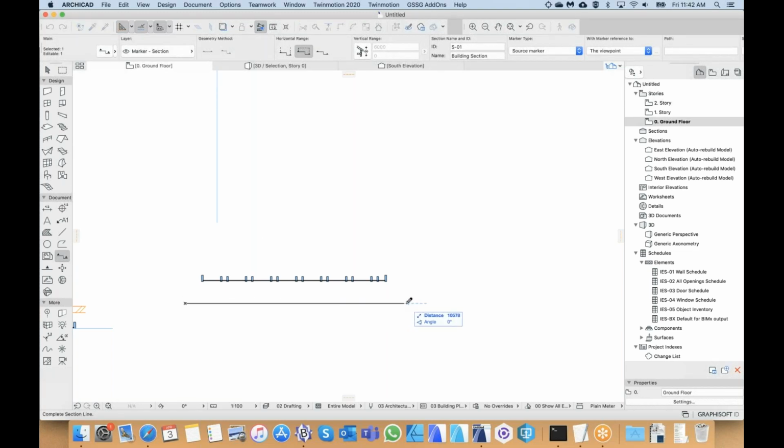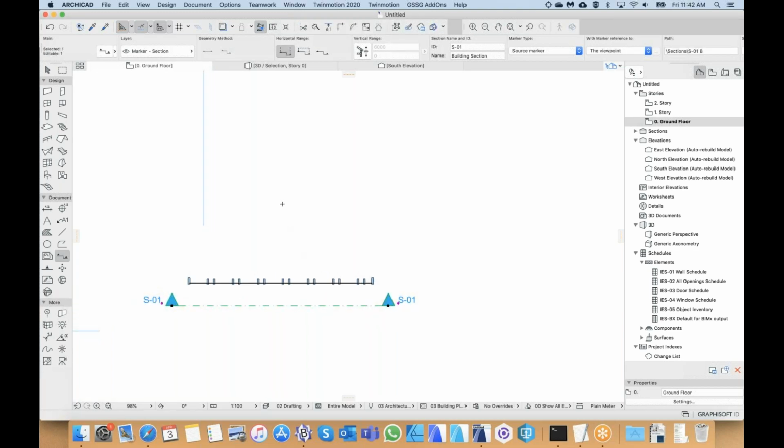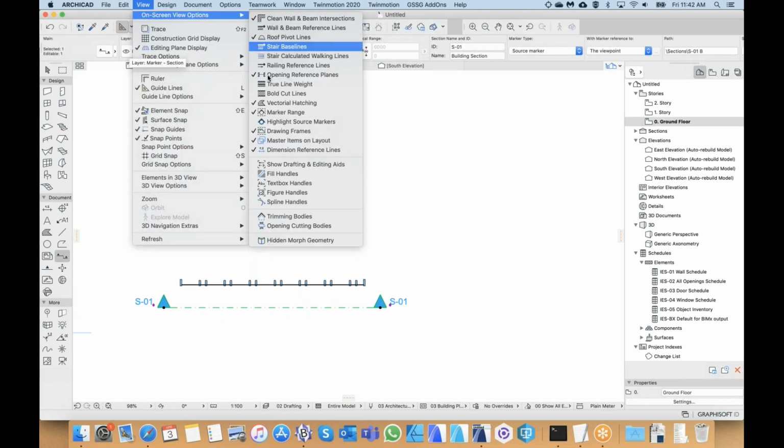So I'm going to draw a section line in front of it, again along the x-axis. So click so it's longer than the Curtainwall, and then I'm going to click behind the Curtainwall, because I want to include this into the limited depth. For some reason, I can't see.